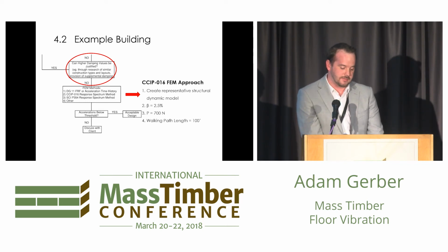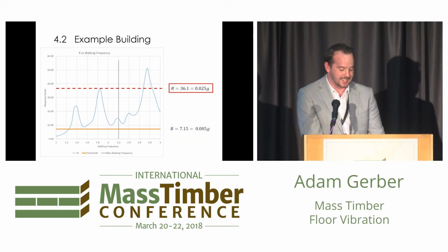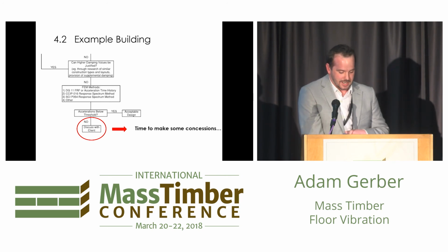So to try and justify that it works, we did a finite element approach, nice little model, sort of modeled all the components with appropriate weights. We got pretty much the exact same frequency that we calculated out by hand and the same participating mass. And 2.5% g, so we were pretty much bang on, unfortunately, with the hand calc from Design Guide 11. So if nothing else, it was a useful exercise to see that the two methods agree. So that forced us to go back and basically have a frank conversation with the client, something which I get to pick up when I go back home.